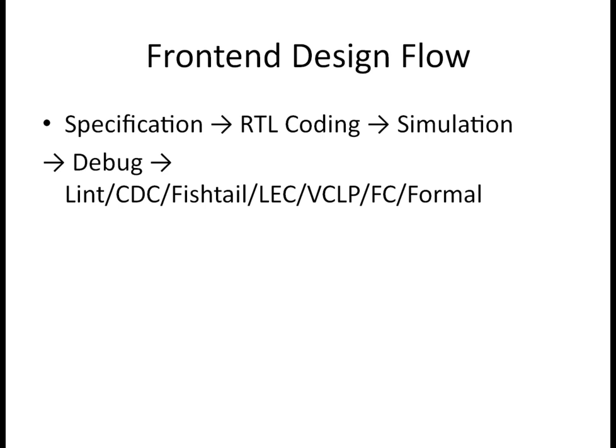So every block has a different speed, and that is obviously intentional. For gaming and similar blocks you want fast clocks, while for calling or any block which you are not going to use often, the clock will be slower. That is a hypothetical example I am giving. Whenever data is traveling from one domain to another, we need to make sure the data passes to the other domain correctly. There are many synchronizing techniques we use, and I will explain a few today.